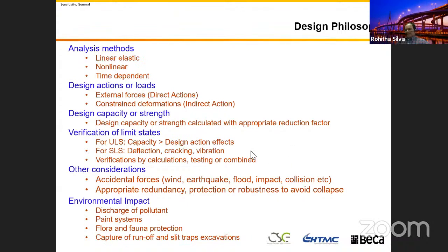And definitely the design capacity, the strength. So you need to make sure that you calculate your design capacity and the strength of your structure based on the proper design standard. For example, you can't use BS 8110 to design a bridge. You have to use the BS 5400 standard.